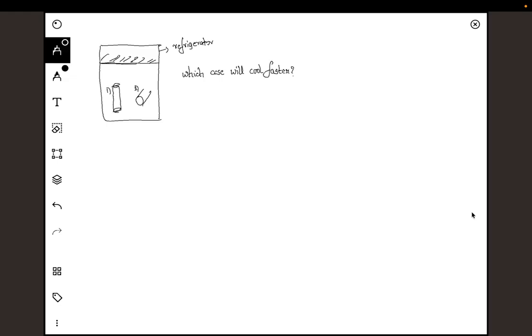First, we have to assume, and this is a very simplified assumption, that whatever is inside this bottle has a very high thermal conductivity compared to the outside heat transfer coefficient, or to put in other words, the temperature is uniform throughout this. So the uniform wall temperature assumption is valid, because unless we assume that it is uniform wall temperature or uniform heat flux, we cannot use any correlation that is there. So I'm assuming that the wall temperature is uniform, which is true when the fluid inside has a very high thermal conductivity compared to the fluid outside. So what would happen then is I'll compare the heat transfer coefficients.